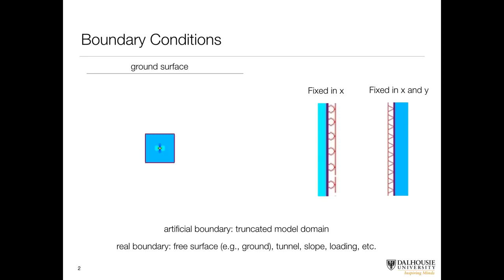In other words, if the model gets too big, it just blows up and really won't solve for you. So you have to come up with a balance of how tight or small of a model you can make and still have enough zones to get a good, accurate solution for your engineering problem.